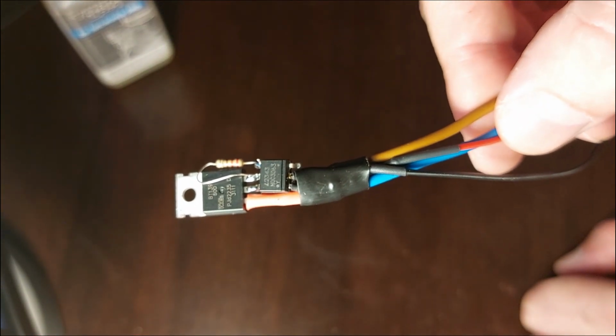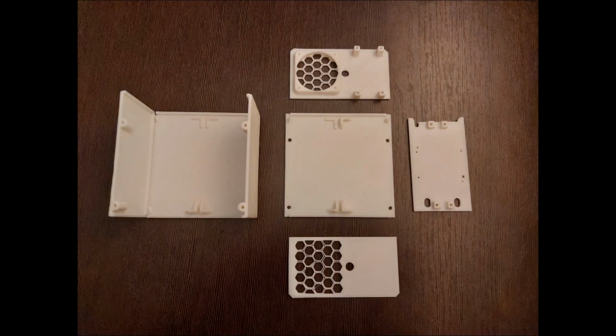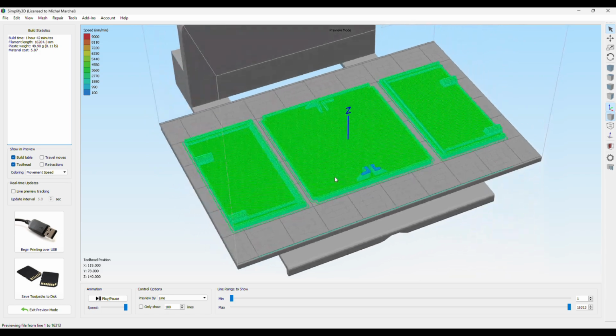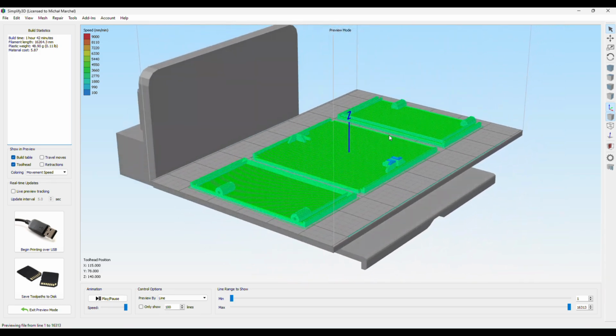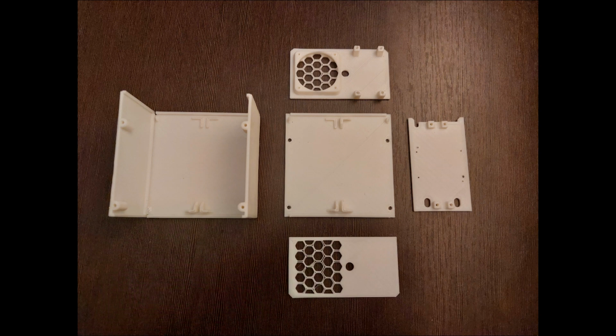Of course, with mains voltage in use, proper electric insulation is a must, so I 3D printed a case for my project. I decided to use ABS filament as it has good mechanical parameters and heat resistance. Downside of ABS is that it shrinks a lot while printing, so to avoid deformations, I printed all walls separately in horizontal position, then stuck them together with acetone. It creates surprisingly strong bonds, I think even stronger than those between layers.